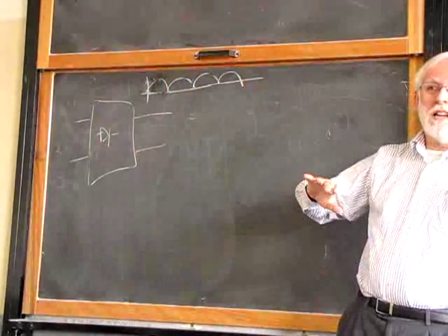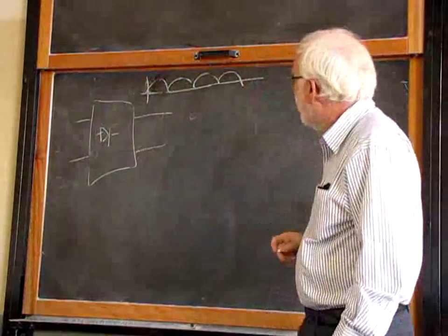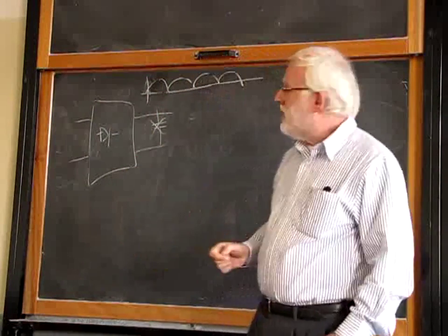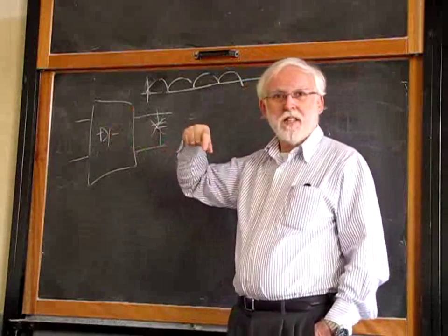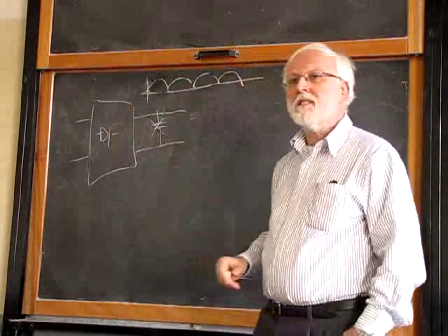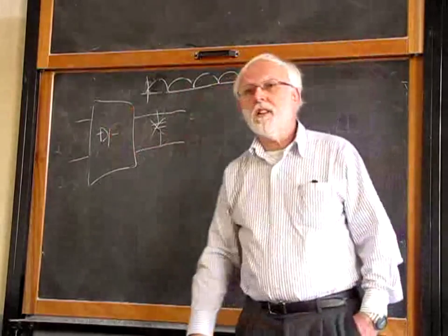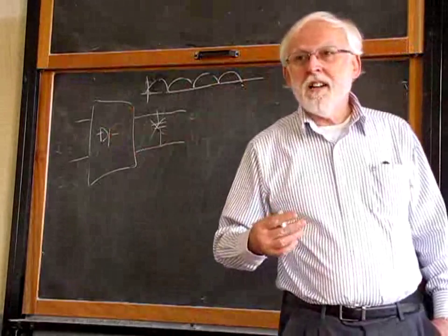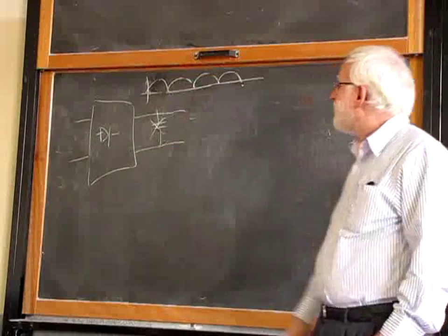So you take the negative half waves and flip them onto the positive side. We cannot place a capacitor here, because the capacitor and diode together make the impulsive current. And then we need some circuit to handle this voltage, because this voltage is absolutely not a DC. Yes, there is a DC component, but this voltage goes from 0 to 300 and some volts.